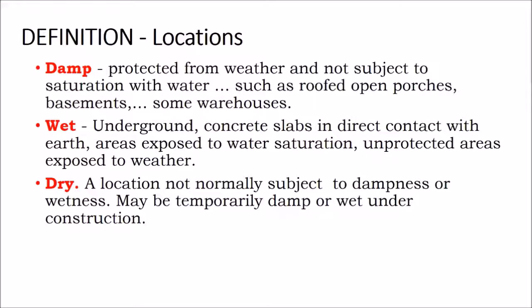Or inverters stored out on a job site with a tarp over them, and they're a NEMA 4 inverter, but then something goes wrong with the construction of the ground mount array. The material sits outside, it rains a while, humidity gets under the tarp and into the box and starts deteriorating the electronics because they're not fully plugged up yet. So don't confuse, if you're designing something for a wet environment, when it's not installed, that doesn't mean it's still rated for the wet environment. That can be a very costly mistake.